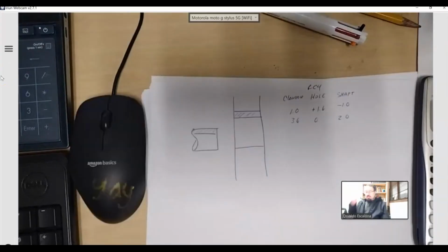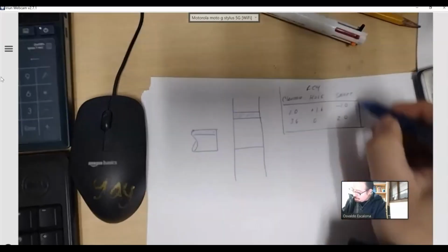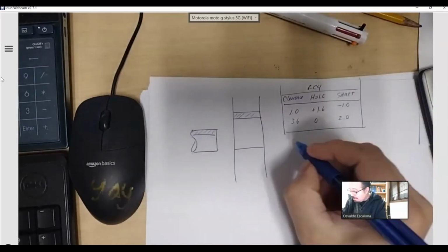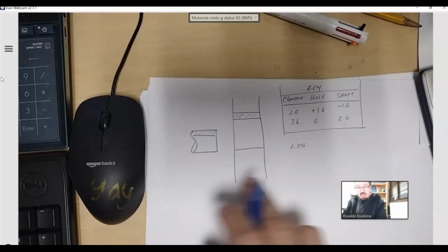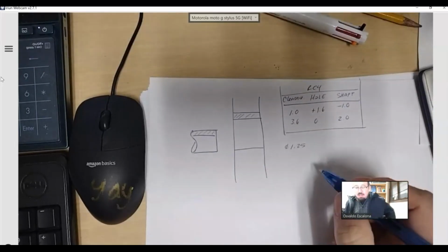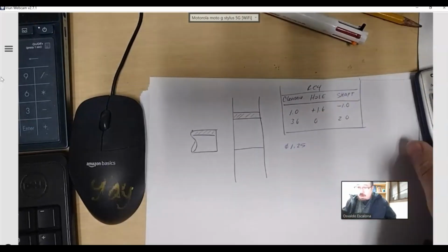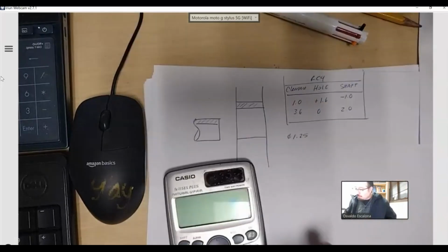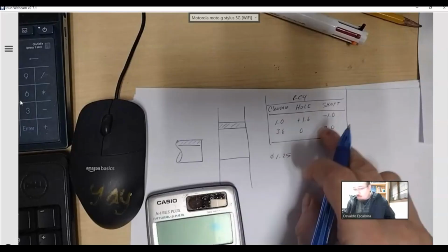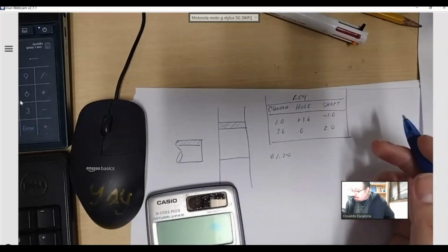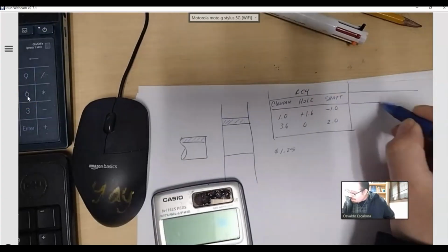Now, how do you work with this? How do you use them? Step number 1, you choose your range for your shaft, which in my case I said was going to be 1 1/4, which is the diameter. The values given to you in these three little slots are in thousandths of an inch, 0.001. So we have to translate this into thousandths. How do you translate it? Thousandths of an inch. You can rewrite it on the side if you want, so you can do it separately.